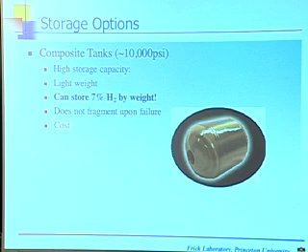Another solution, the solution that the Department of Energy by far favors at the moment, is they say tank technology is a good technology, steel is bad, so let's go to these composite tanks. The composite tanks today are rated for 7,000 psi. It's a carbon composite, a wound carbon filament. The inside of the tank has a polyethylene sleeve, which is necessary to keep the hydrogen in there. It'll leak out of the carbon windings otherwise. It is believed that they will be rated for 10,000 psi in the not-too-distant future.